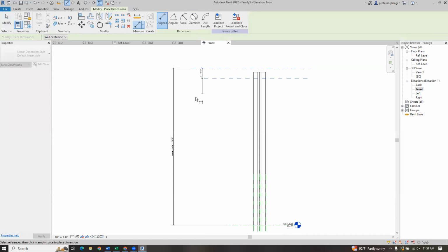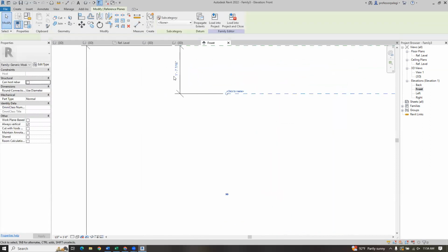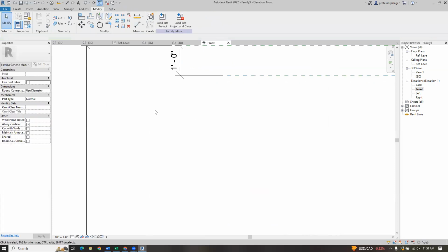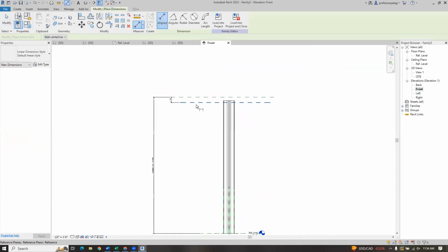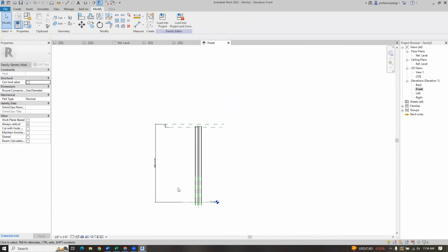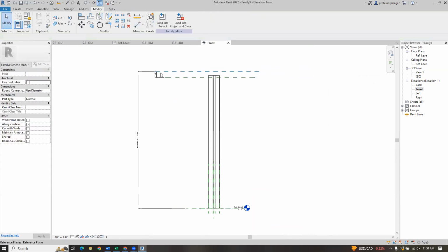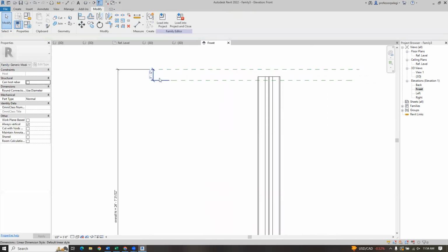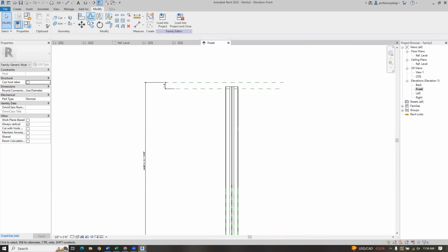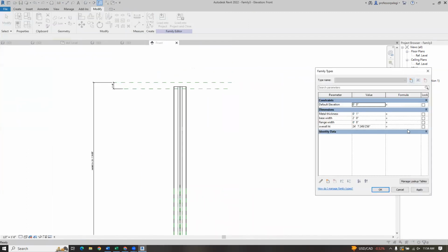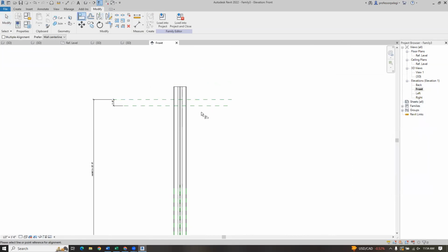So watch, I'm actually dimensioning this from up here. So I grab this, and I'm going to say 1 foot. Notice I did not dimension from here down. I didn't lock, so watch. If I was to do the dimension from here to here, those are competing and locking against each other. So I can say, hey, no matter what, I always want this to be locked at a foot. Now I can come in and change my height to 22 feet. And that goes out, but hey, the column didn't move. Well, it doesn't matter. That's just, hey, that and lock.